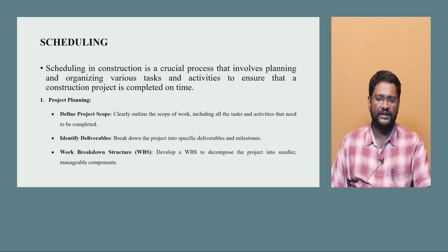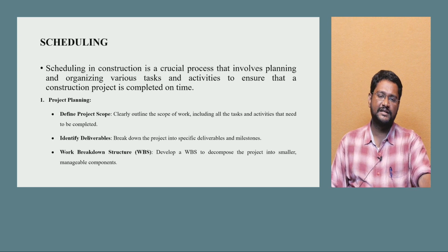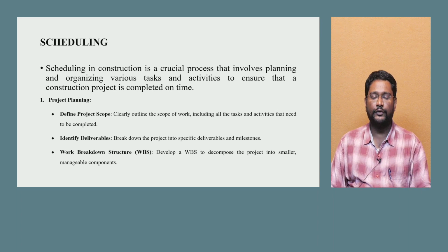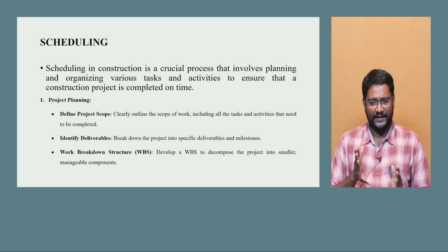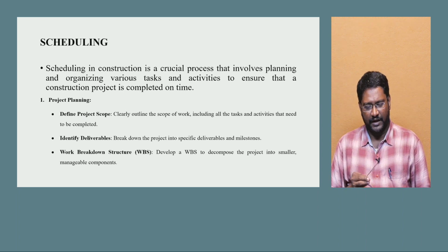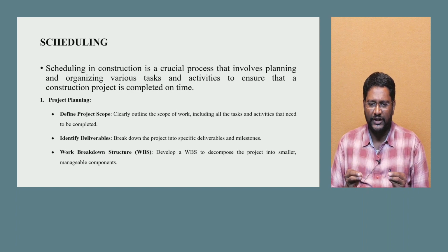Okay, identifying the deliverables. So break down the project into specific deliverables and milestones. For example, we are going to construct a G+1 structure. First of all we have to divide it into two parts, substructure and superstructure. In the substructure also we have to divide the scheduling into parts. First of all we go with the PCC, plain cement concrete. After that you have to lay the footing, which may be isolated footing or deep foundation, maybe pile foundation or mat foundation. Depending on that you have to break the schedule into different parts.